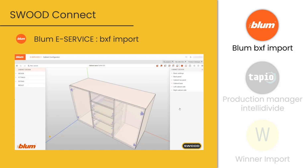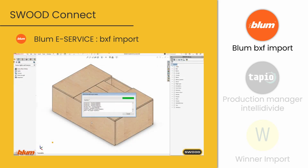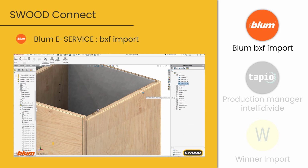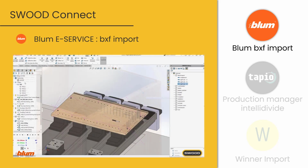And let's start with the Bloom import. For years now, Bloom created an online furniture configurator named Bloom eService. Download your products and simple projects from this platform as a BXF file to directly import it in SOLIDWORKS and SWOOD. Thanks to the Bloom import features, you will be able to add SWOOD information such as materials, connectors, processes, SWOOD box to create your CAM program for your CNC and generate reports with all the needed information.